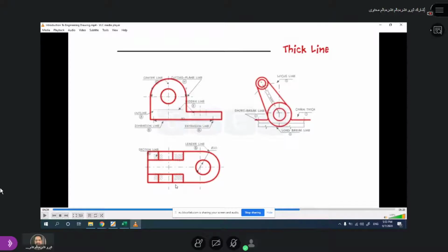So whenever you find any thick line, that means that is the edge of a component. Thin lines are generally used for some other purpose. That's why whenever you draw the line thickness, dark line, light line, is it a straight line or an axis line or maybe a dotted line? All are very important. The engineers will understand about the component by watching the line itself.